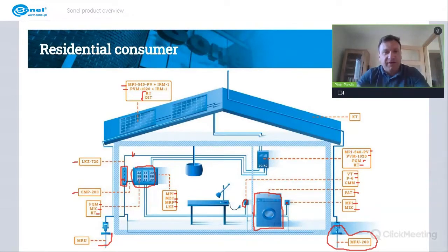So to sum up the earthing in residential buildings, if they have solar panels, then we treat them as the solar power plant, and we need MRU 120 or 200. In case of thunder strike, MRU 200. And if this is just a regular grounding system, then we can use any of the meters from the MRU series. Now, further on, what we can check in a residential building.